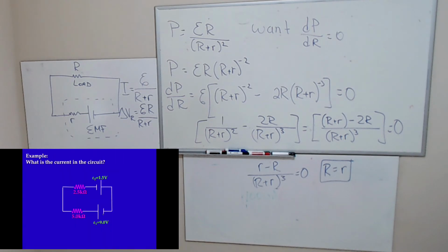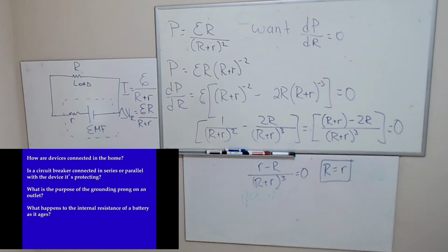We talked about this already. So anyway, what I like about this is there are probably a lot of practical things regarding things in your house. For example, you can't just plug all kinds of stuff into your socket, right? Imagine plugging in 2 vacuum cleaners. I've seen people do that. If they're the old vacuum cleaners and you turn them on both at the same time, guess what's going to happen? You're going to trip the circuit breaker because you're drawing too much current. Okay, the sockets are 20 amps.